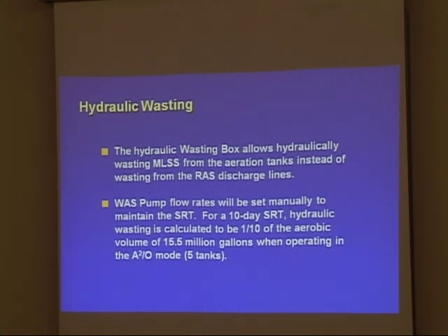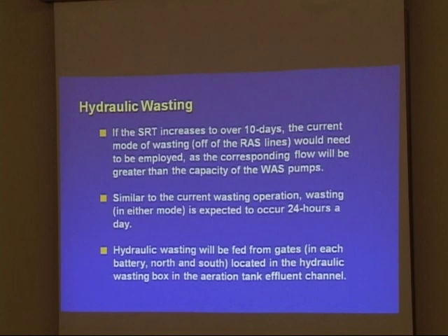So for a 10-day SRT, you just calculate 1/10 of your aerobic volume and set it to waste that amount, and it automatically will be maintaining an SRT of 10 days. So this is a very foolproof, simple way of doing it. I don't have to sit around and keep cracking numbers, just going by volume.